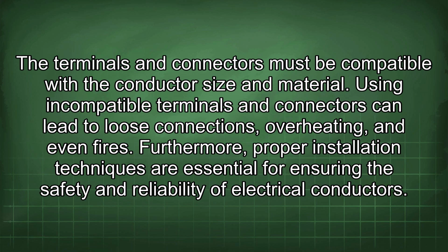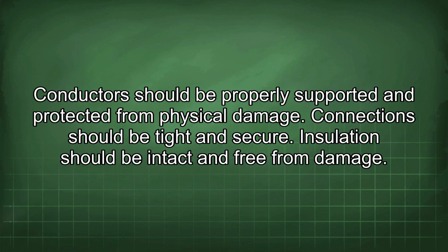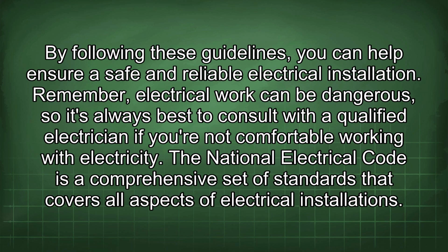Furthermore, proper installation techniques are essential for ensuring the safety and reliability of electrical conductors. Conductors should be properly supported and protected from physical damage. Connections should be tight and secure. Insulation should be intact and free from damage. By following these guidelines, you can help ensure a safe and reliable electrical installation.